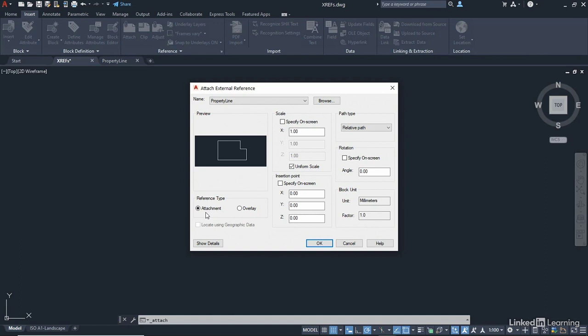It's a permanent setting. If you set it to overlay, what will happen is if I Xref a file into a host drawing, and then let's say I Xref the host drawing with the attached Xref into another drawing, that Xref that's been attached initially will not display. Now, it sounds very wordy, but the best way to do it is to test it.